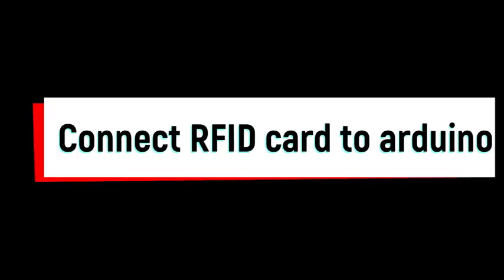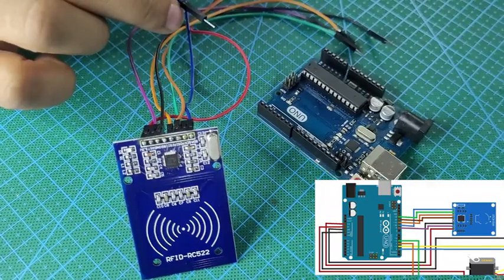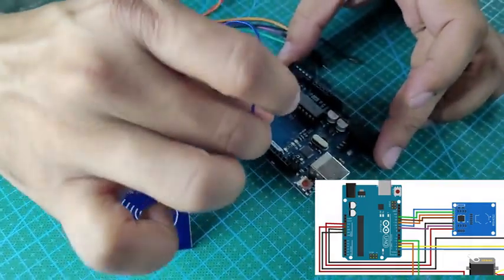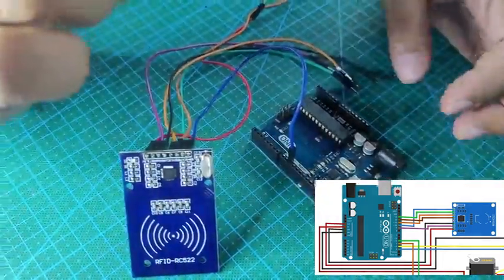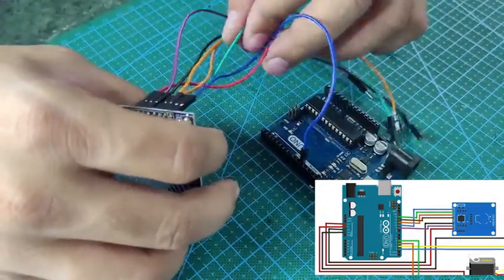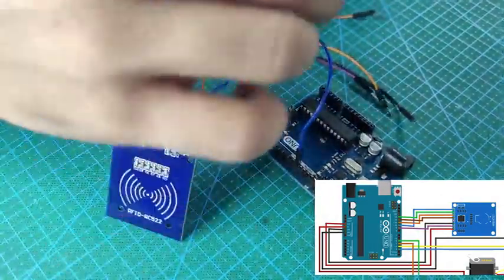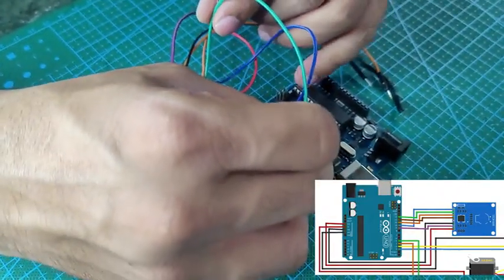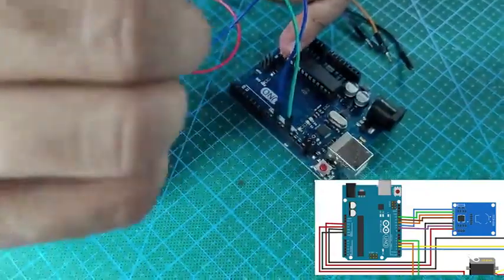Now, connection of RFID card to Arduino. Let's make that connection as per the circuit diagram shown in the bottom right. Right now I'm not going to call out the pin numbers, but yes, the blue wire is connected to pin number 10. The green wire is connected to pin number 13.